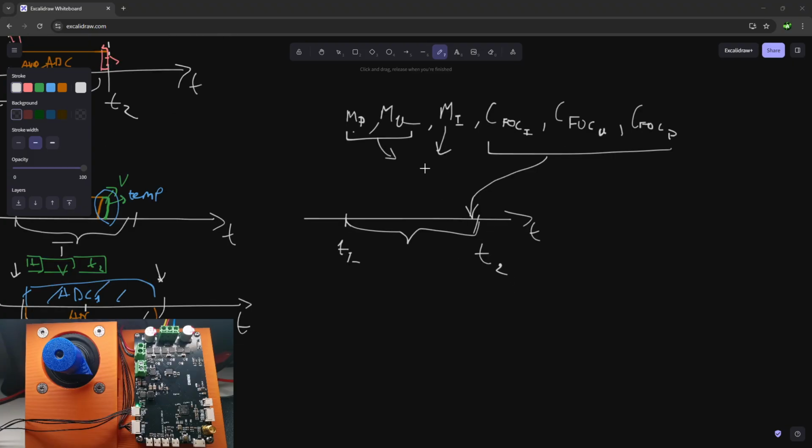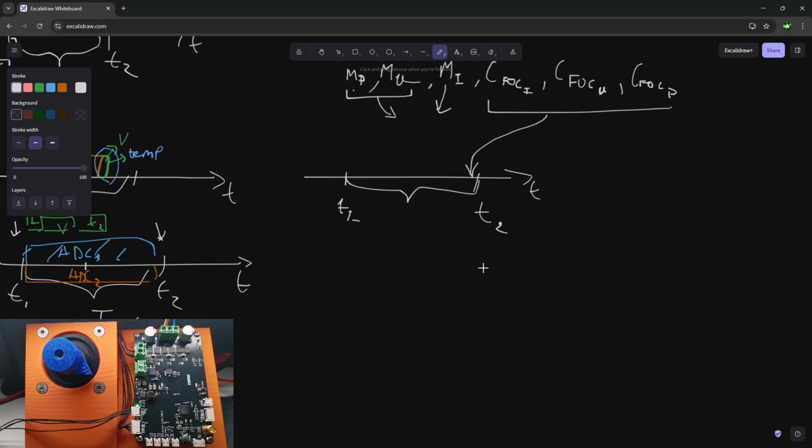What I was talking about is why we need to be very late in the period. When we finish here, it means that we update our next PWM period very close to the moment it's called. So let's say our period was like this and we update it to be like this, and this update will be more precise the later in the period we do it. So this means that we would like all our calculations, all three of them, to be here.